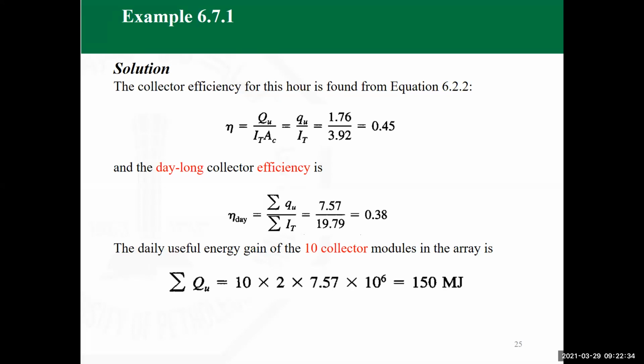What would determine that? It's an economic factor, which is basically what we call the payback period. If you are going to use a 50% or 60% solar fraction, actually typical values are somewhere between 50 to 70%, then you are going to pay for the solar collectors, and you are going to have a payback period of several years. If you have electric heating, the number of years is small, it's a short period.